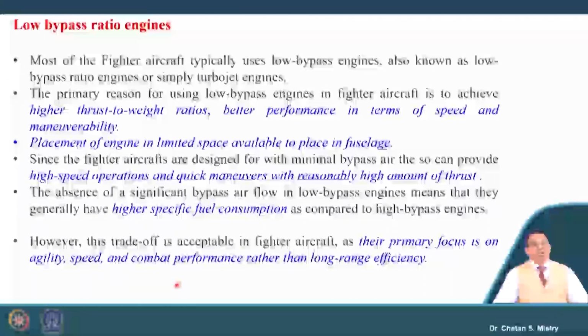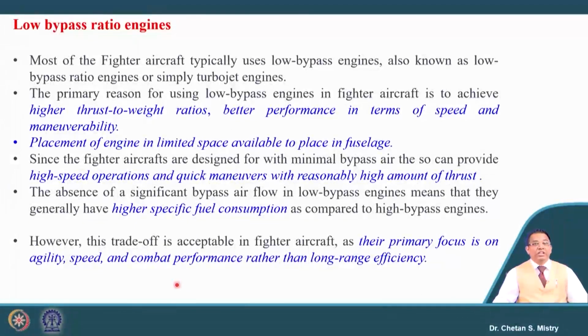One major attraction is that we need to accommodate this engine within the fuselage, where we have limited space. At the same time, for high speed operation and quick maneuvers, this gives reasonable thrust. But for passenger aircraft applications, where we are looking for lower specific fuel consumption, this is not beneficial.